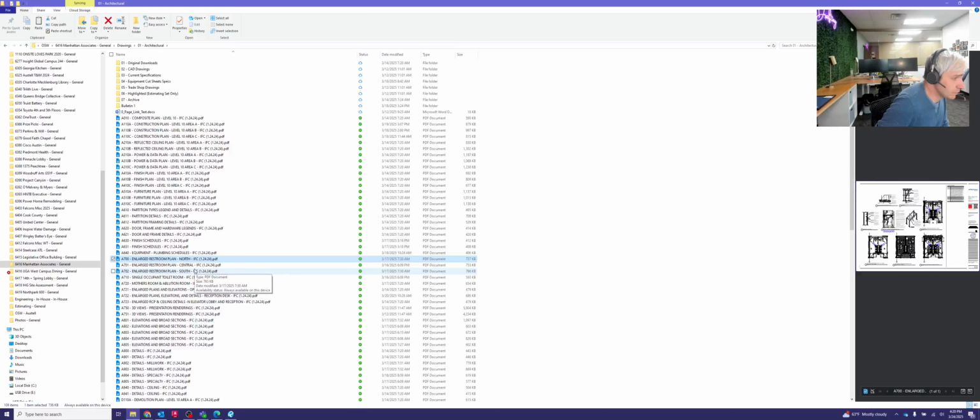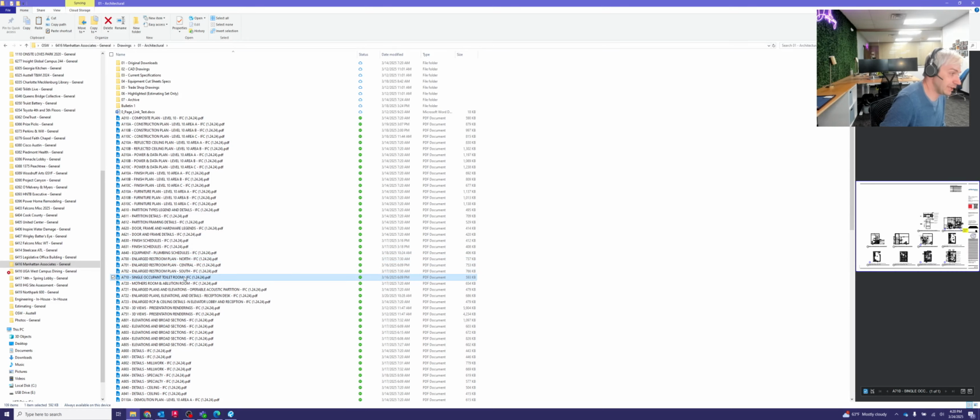All right, so sometimes you will be given enlarged plan views too. Enlarged plan views are exactly what they sound like. They take a portion of the building and make a blown up view of it, a more zoomed in version of the drawing, so you can show more detail of what's going on in that room. We'll talk about how to locate those on the floor plan shortly. Those are just, again, more detailed plan views of a specific part of the building.